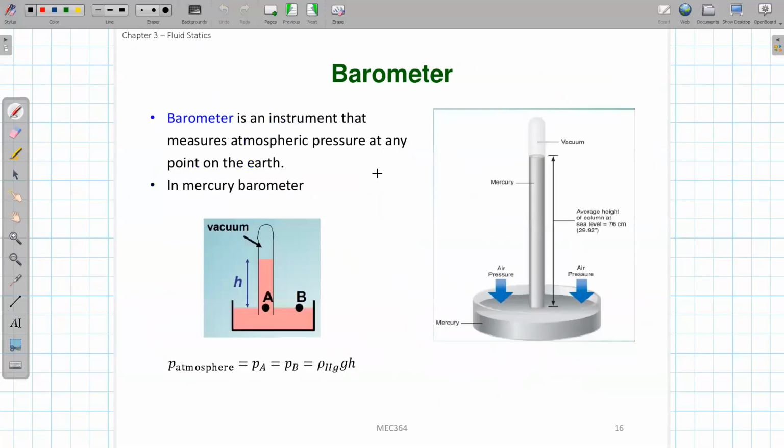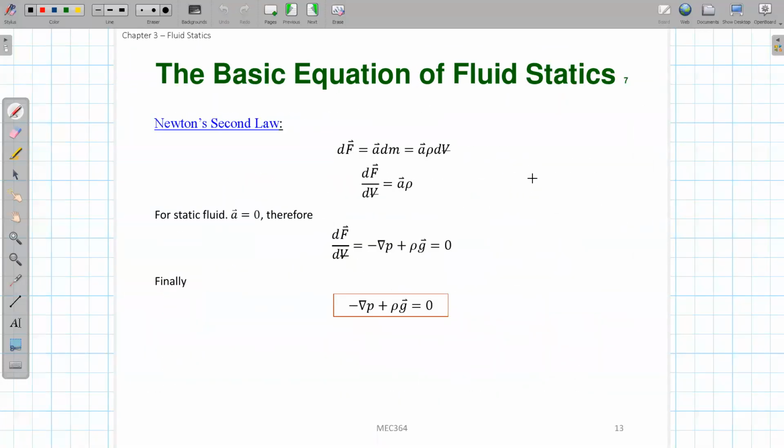Okay. I didn't write it here, so let me quickly draw it. For the pressure force, for the normal pressure, it depends on the surface normal N, and maybe you have a force here. For the normal direction, this is the Y location and force delta Fy. Because this is a positive Y direction surface and also a Y direction force, for these cases it will be a negative value. Why? Because this normal direction and this force direction are not in the same direction. If they were in the same direction, then it would be larger than 0. So this is for the normal force.